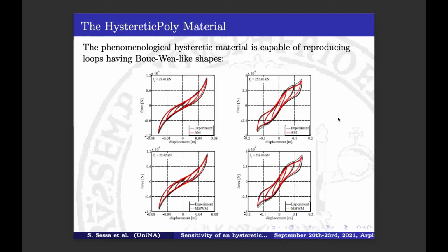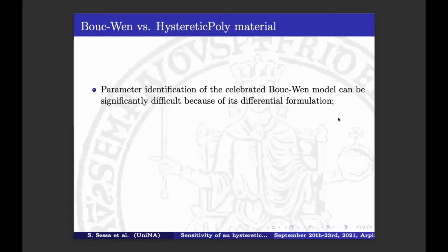So we often stress the similarity between our model and the Bouc-Wen one. This is because, besides the fact that the two formulations are completely different from a mathematical point of view, they provide shapes of the hysteresis which are quite similar, and they have some common properties, such as the fact that they are smooth and can implement pinching, hardening, softening, and even local minimum and maximum.